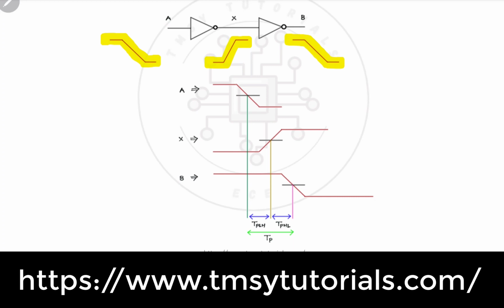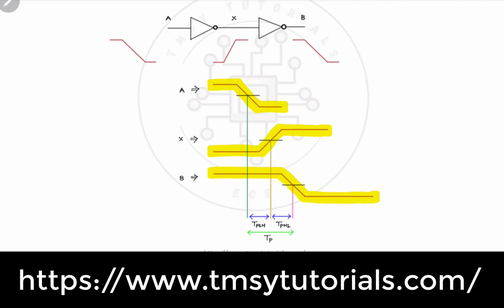So always, if you want to calculate the propagation delay, it should be calculated with respect to the input at A and the output at B. So let us see this waveform now. The input is falling from high to low, and at X it will get inverted, so it is low to high, and this X will be the input to the second NOT gate. So at B I'll get high to low, simply inverted.